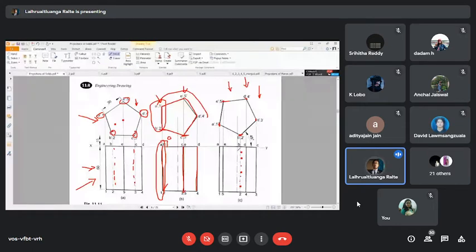Suppose this 45-degree alignment was done incorrectly and is a little more than 45, so the E5 line is oriented in such a way that it slightly overlaps A1. Then your A1 line is going to be dotted in your representation, because it is slightly beneath the E5 line. If that is the case, your projection is going to be rendered wrong.